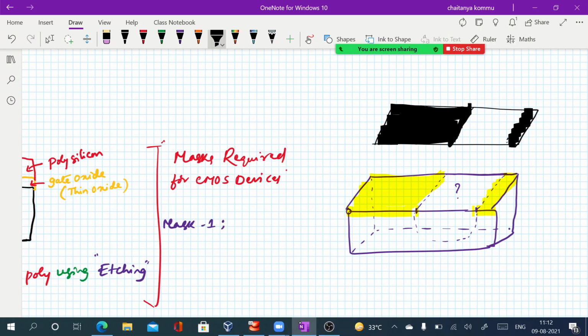So whatever material is on top of the covered portion cannot be affected by this mechanism. We send the UV radiation, open the window, and diffuse something at this point, while other portions cannot be affected. Therefore, this is called a mask.